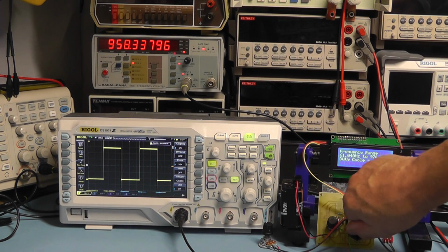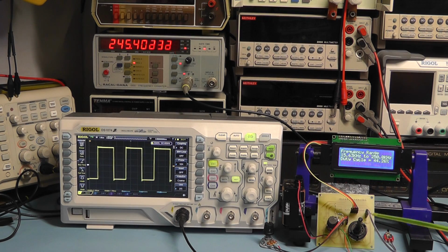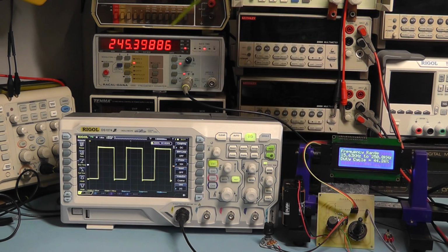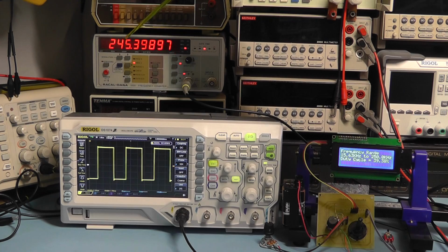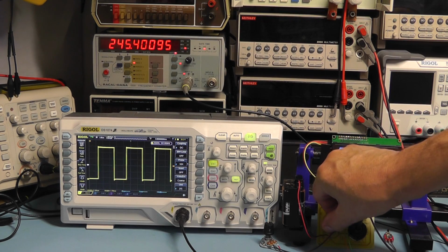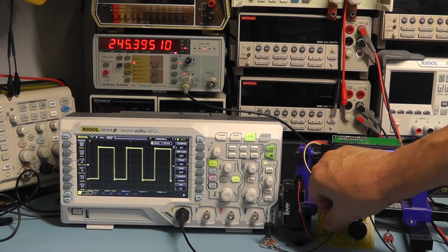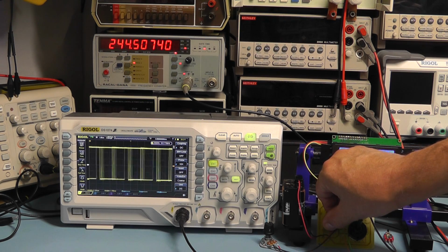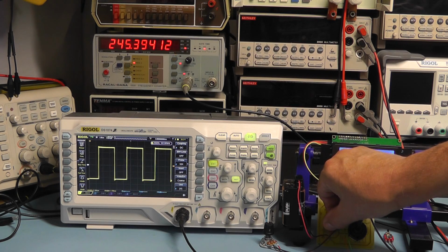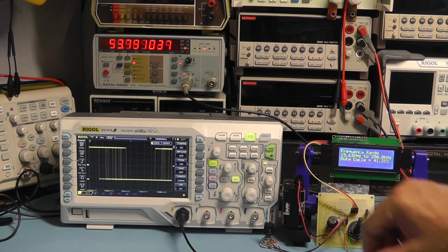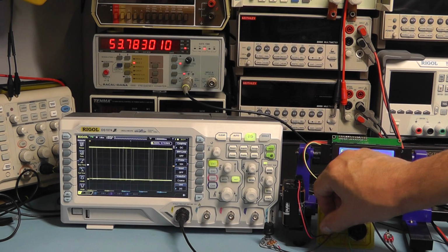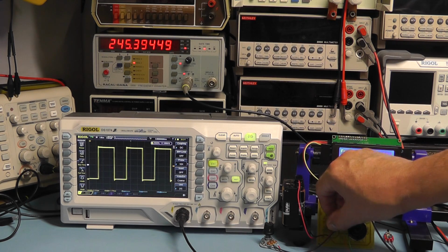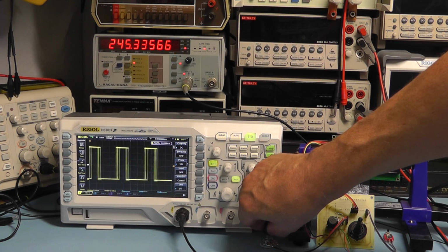Let me just go up another frequency range. I've now got the frequency selector switch for the range 15.63 kilohertz to 250 kilohertz, and we're towards the top end of that at the moment, so we're showing 245. Again, I can alter the frequency control here, and this time we get a lot of noise as we adjust that frequency. And it takes a while, I think, to settle, so we need to have a look at that. Again, we can alter the mark space ratio.